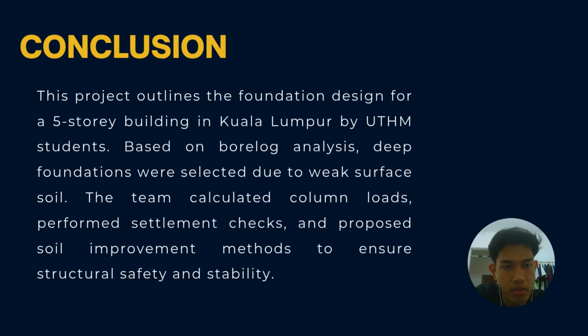So next for the conclusion, this project focused on evaluating the soil condition and designing a suitable foundation system. So our team analyzed borelog data, including unit weight, corrected N values, over-consolidation ratios, and friction angles to understand the subsurface conditions. Based on our results, deep foundation was selected due to inadequate surface soil strength, with settlement checks confirming its effectiveness.